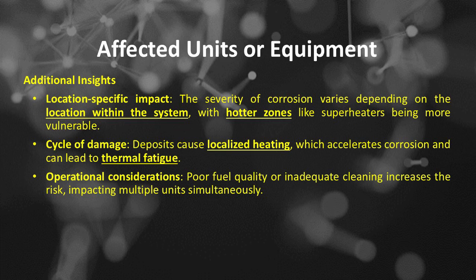Additional insights. Location-specific impact: the severity of corrosion varies depending on the location within the system, with hotter zones like superheaters being more vulnerable. Cycle of damage: deposits cause localized heating, which accelerates corrosion and can lead to thermal fatigue. Operational considerations: poor fuel quality or inadequate cleaning increases the risk, impacting multiple units simultaneously.